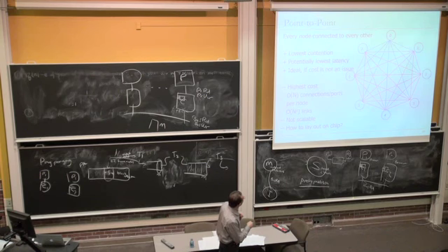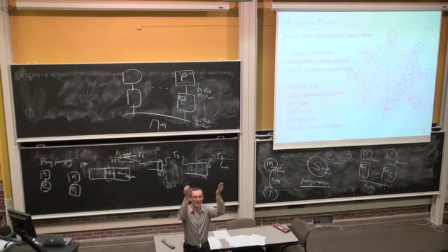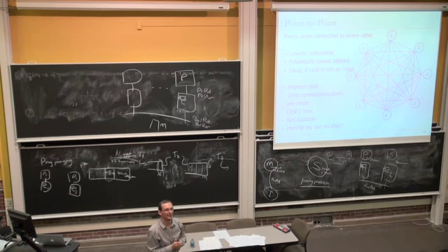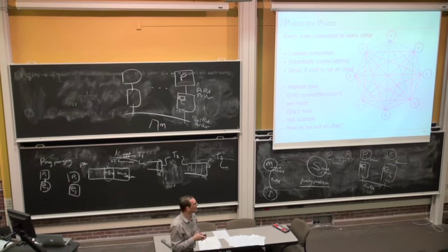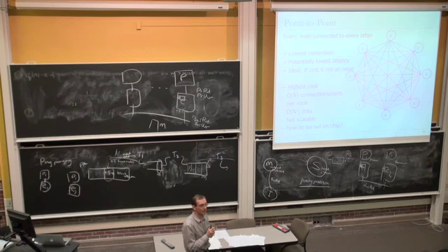Okay? How do you lay out on chip? Let's say you implement a 1,000 core processor. How do you lay this out on a chip? That becomes a little bit hard also, right? Because although it looks regular, how do you actually do these connections on the chip? You don't have that many wiring metal layers, especially if you want to add 1,000, 10,000 cores. Okay, that's something to think about because today we're putting many processors, many cores on chip, and this is an important concern.